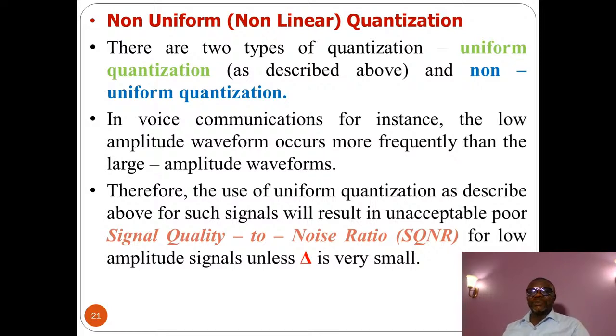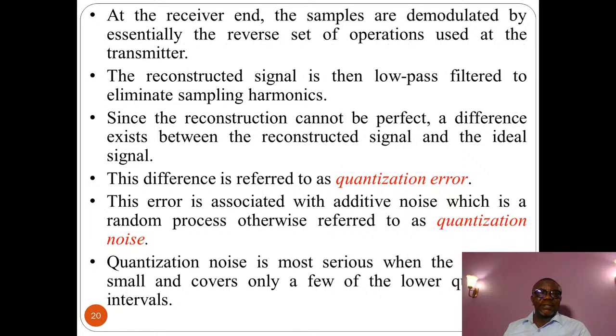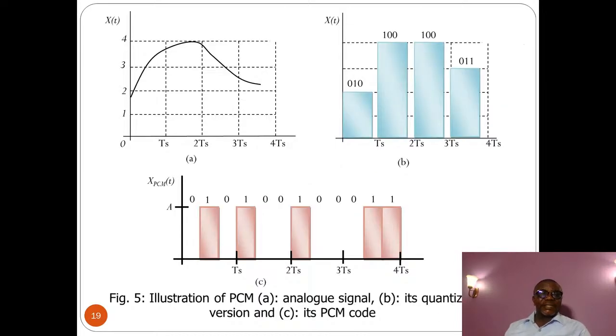So it becomes difficult for you to now do this quantization. The signal may fall within the same amplitude level. To get what we are saying here very correct, if you look at that signal, figure A, what if this signal starts between 1 and 2 and till the end it remains between 1 and 2? There are no peaks that crossed 2 to go to 3.